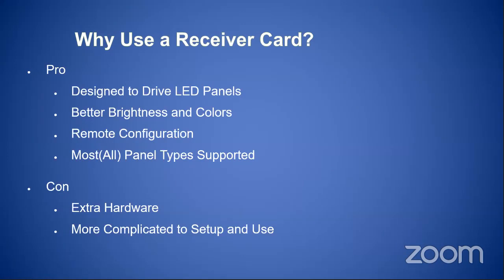And the reason for that is once you start doing a lot of graphics and a lot of other things on it, it's going to start giving you a rippling or tearing, an artifacting that you're going to see on the screen, just because there's so much data going over the lines. And the BeagleBone can get pretty close to what a Colorlight can do in speed, but the more panels you add, the more stress it puts on the processors, and it just can't keep up with the refresh rates that the Colorlight can do.